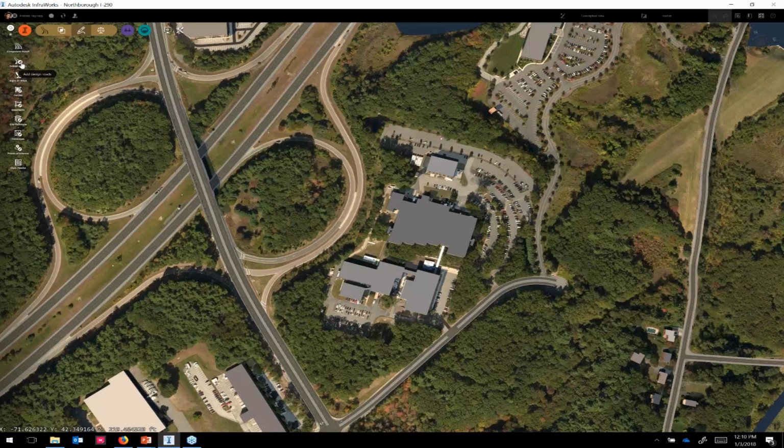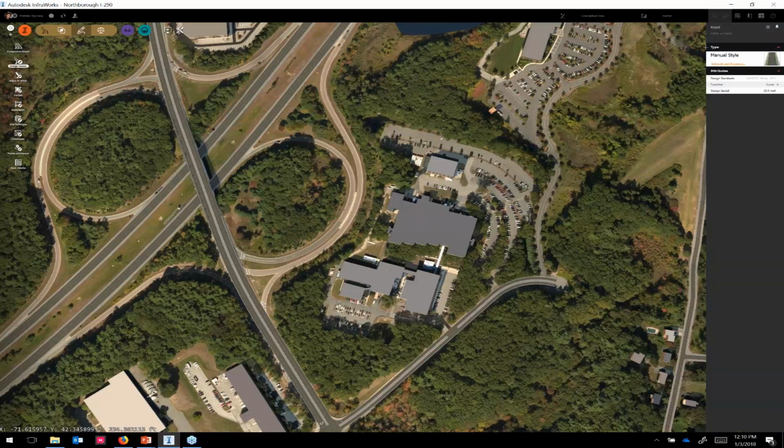It used to be, in the previous releases, that we had a tool for highway, collector, arterial, local, defined by the design speed and function of that road. But now we've merged them all into a single tool called design road. What happens when you invoke this tool is you'll see a stack approach, which is like a property set of attributes which you could set up even before you start laying out the tool.